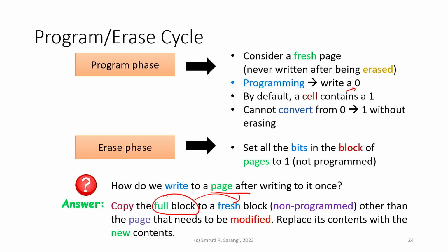So the idea basically is that, if you are moving a full house with a lot of furniture, you are not allowed to change one sofa in a house. As illogical as it may sound, it is like moving all the furniture from one house to the other. But if you are not interested in a sofa, then don't take it and buy a new sofa, right? That's unfortunately the way it is. That is why DRAM caching becomes very important, very, very important, to precisely reduce such occurrences, because these are very power hungry and slow operations.